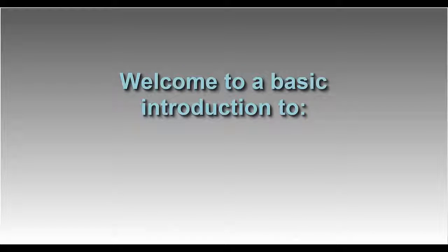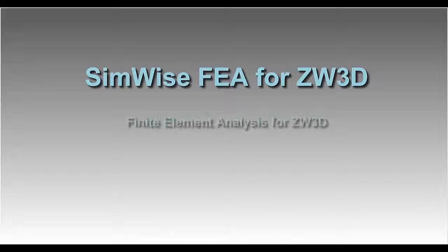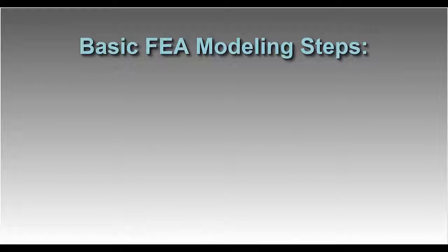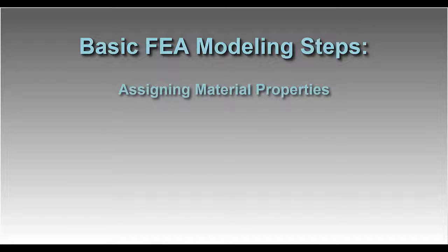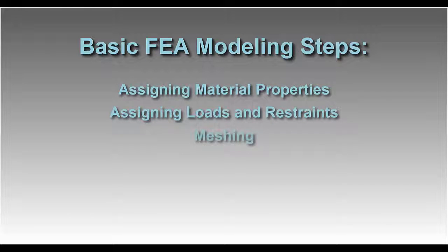Hello, and welcome to a basic video introduction to Simwise FEA for ZW3D, Finite Element Analysis for ZW3D. In this video demonstration, we'll look at the basic steps involved in setting up and analyzing an FEA. That involves assigning proper material properties, proper loads and restraints, meshing the model, and then finally post-processing the results.